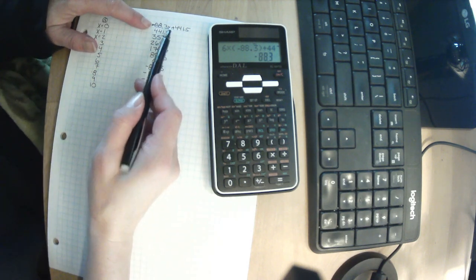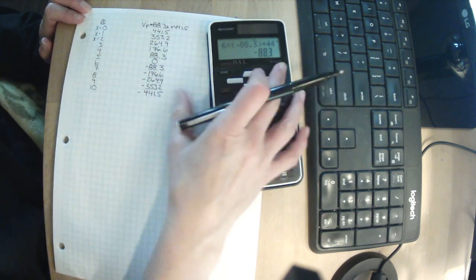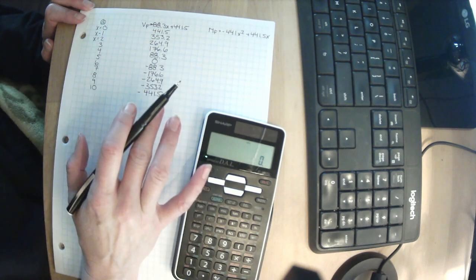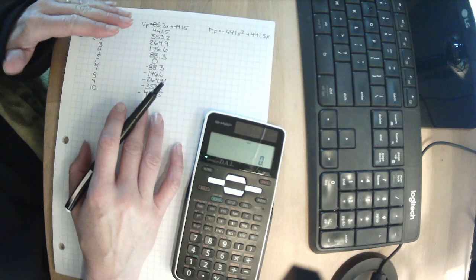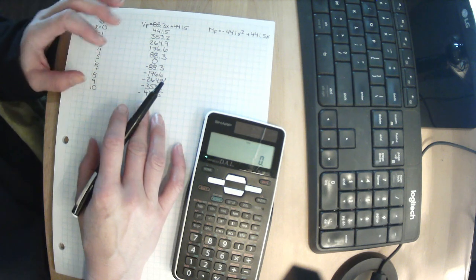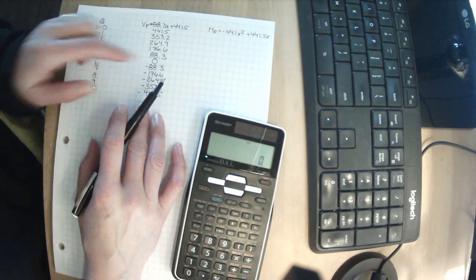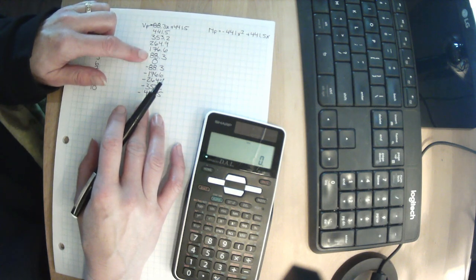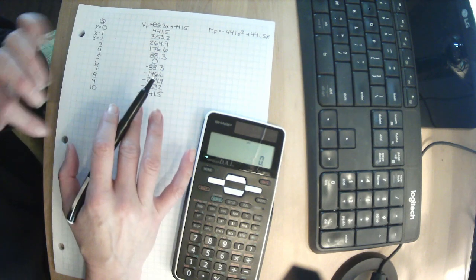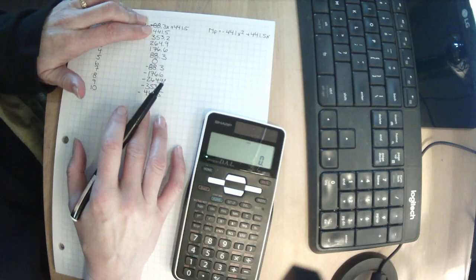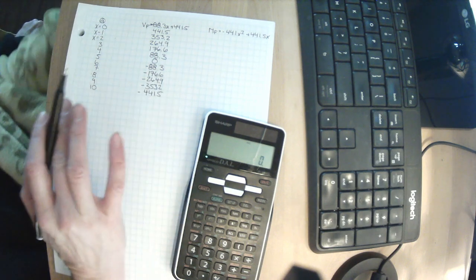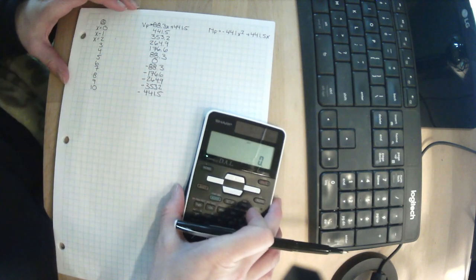Had I kept these the opposite way, all of this just would have flipped. Remember I said in shear, positive or negative doesn't actually have any real meaning. The reason we like to keep track of it is it tells us when it flips the axes, when it goes from one side to the other. So we need to keep track of it just so we can see where we cross the axes or where it hits 0. But whether this side was negative and this side was positive, or this side was positive and this side was negative, is irrelevant. I tend to consistently do it so that the left-hand side of my equation is positive. But it's not something to get too fussed up over.